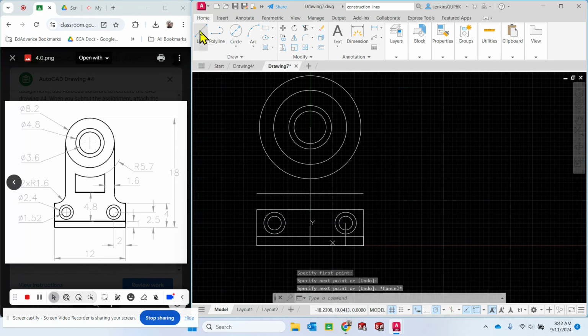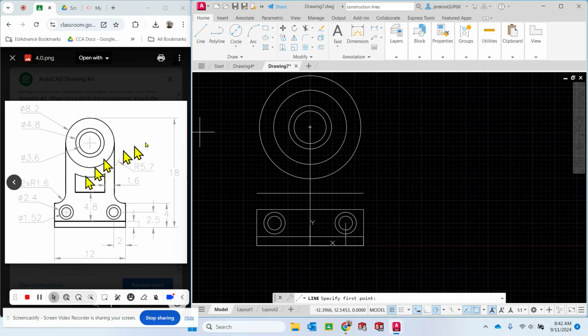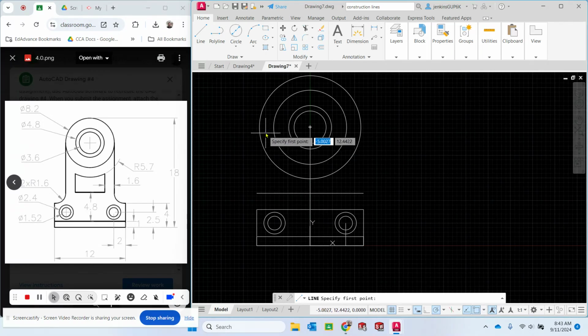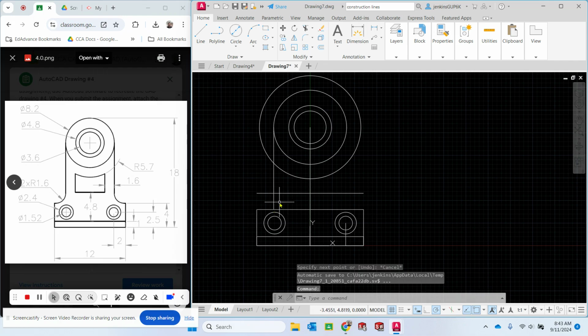All right. I'm now going to make a line that goes, so I'm trying to draw this line here. Offset it over. So I go down from here. When I hover over this part of the circle, you can see it turns green. If it doesn't turn green for you, go over here to what you want things to snap to, and make sure that quadrant is clicked on, and then it will make sure it snaps to it. Okay, so I go over here and I click on here and just go straight down until it lines up with that. Awesome. All right.